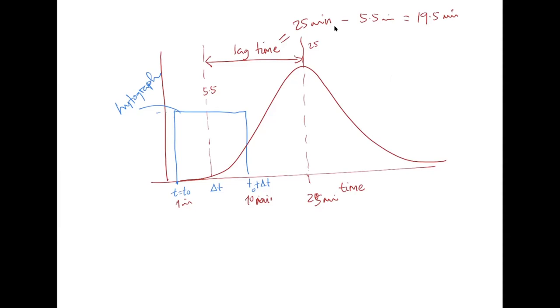So what if the hydrograph's not flat? Would we just be taking the average between t naught and the end? You'll just identify, let's say I give you something like this. So we just choose a midpoint every time? Yeah, you can decide. Usually you use the centroid. That's the weighted curve. But if graph-wise you cannot find it, just pick any location and say this is the center. Okay, got it.